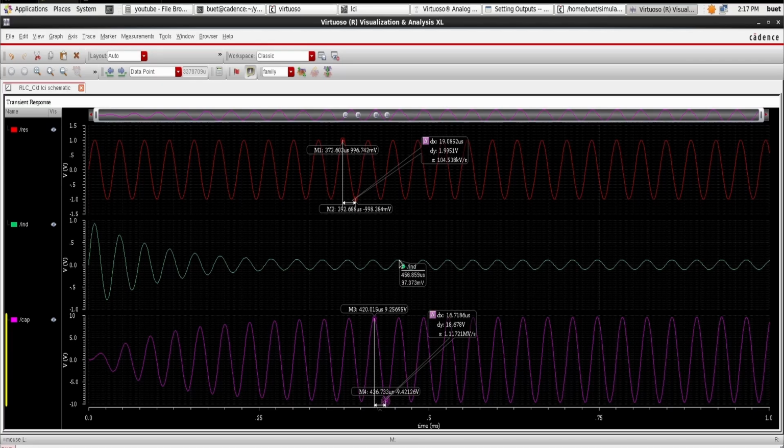We can see why. Plotting the voltage across the capacitor is straightforward because one terminal is connected to ground. However, for the inductor, neither of the terminals is connected at the ground potential. If I directly probe a node, I won't obtain the actual voltage across the inductor. To measure the true inductor voltage, I need to take the voltage difference between its two terminals.